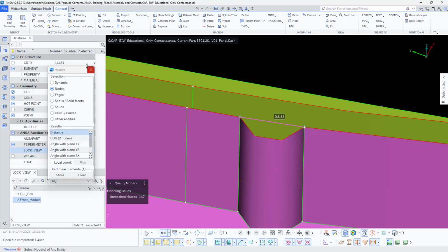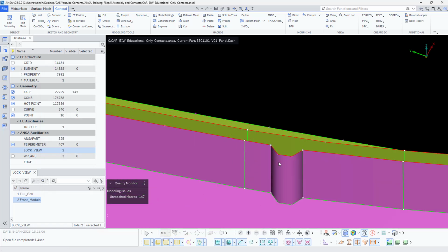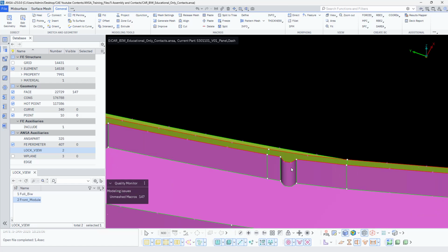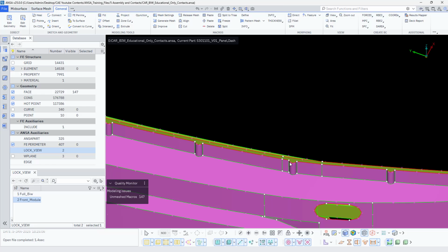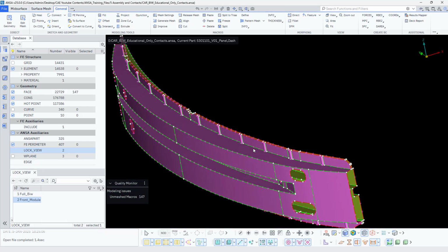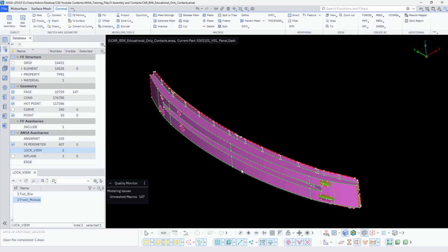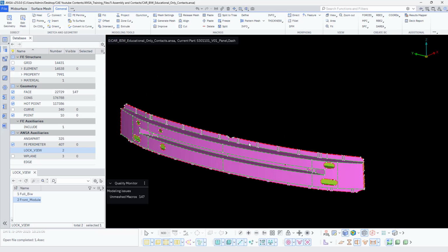It's on average 8, so with a 4 mm mesh it will be only 2 divisions, whereas I would like to have 4 splits. If you want to maintain this geometry, it will be quite difficult with a 4 mm mesh. In industries, 4 or 5 is standard, depending upon the requirement again. Right now, with my interest, I would like to go with the 4 mm mesh on this.